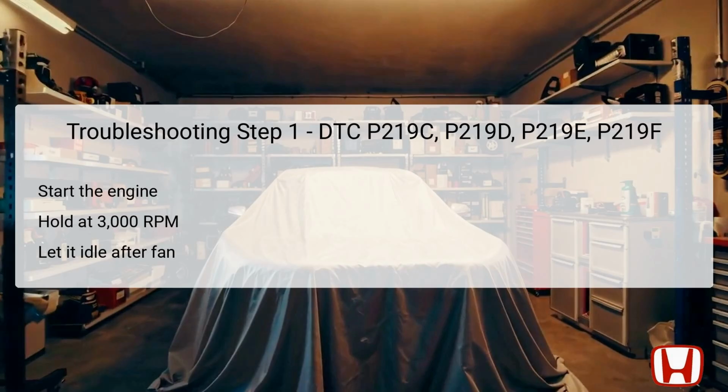Additionally, holding the RPM can help reveal any immediate irregularities in the engine's behavior or codes that the PCM may trigger in relation to air-fuel ratios. This setup prepares the technician for more stringent tests that will follow in the troubleshooting process.